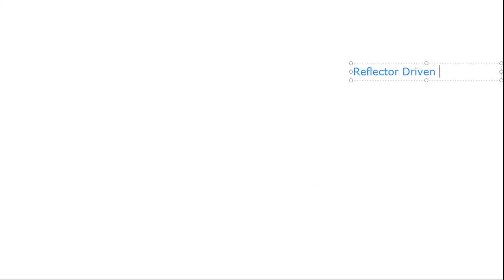And the third one is the director. If there is one element, this is a director. If there is more than one element, then there are directors. These directors will direct the radiation pattern in a specific direction. So for this, the directivity of the antenna will be increased.